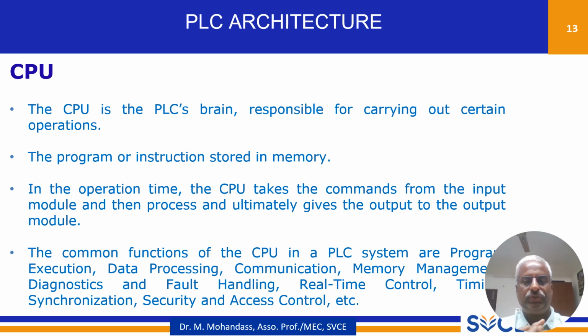We are going to discuss the input module and output module after finishing this CPU. So I think you can understand the function of CPU now. It is the brain which is essential to execute the program and read the information from the sensors for producing certain outputs to operate the actuators or machines. The common functions of CPU in PLCs are